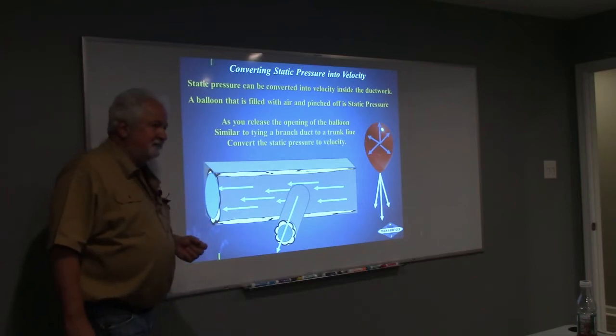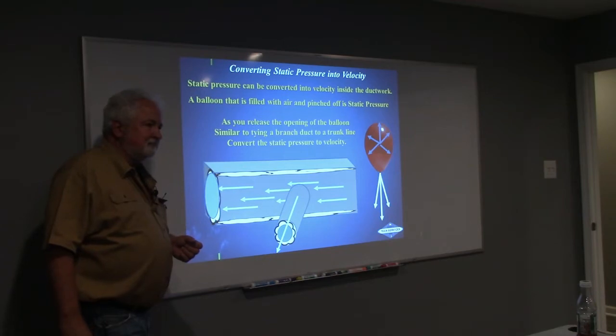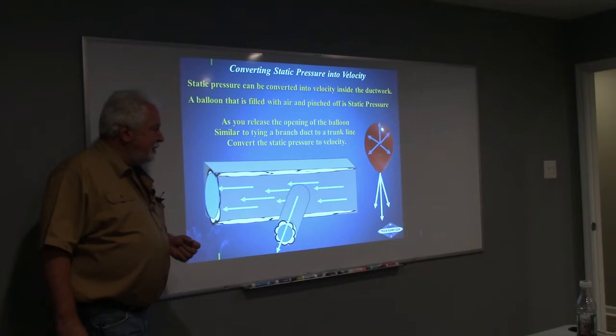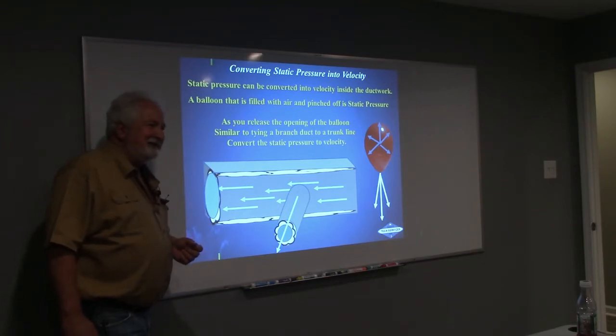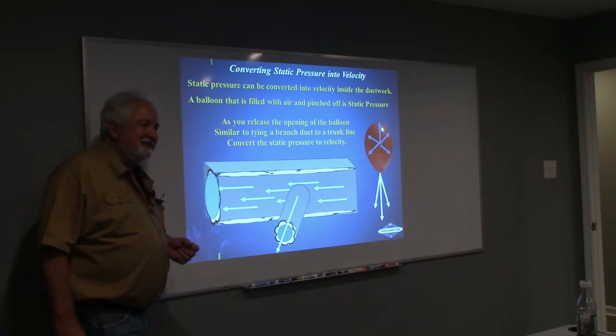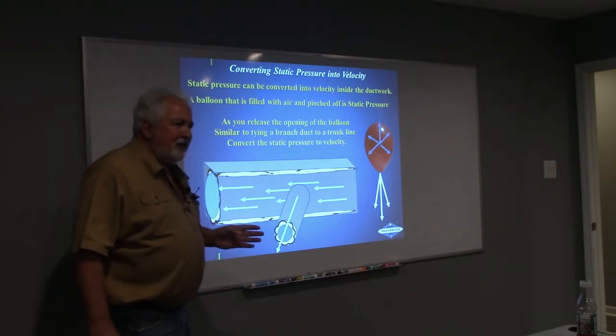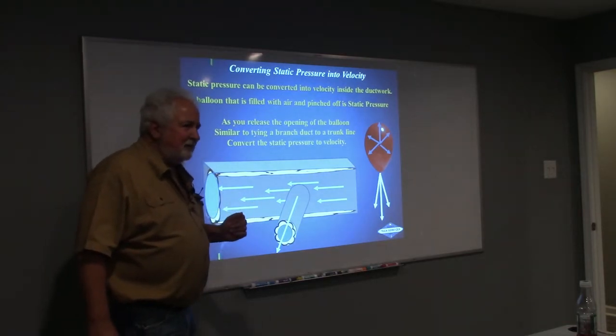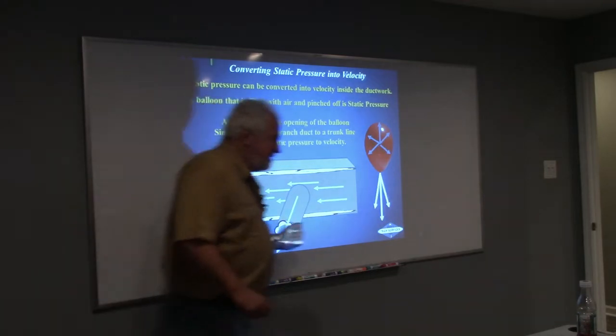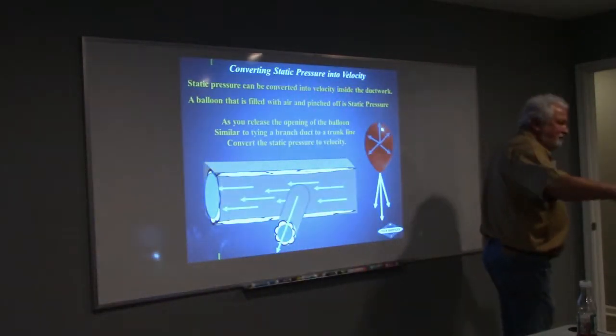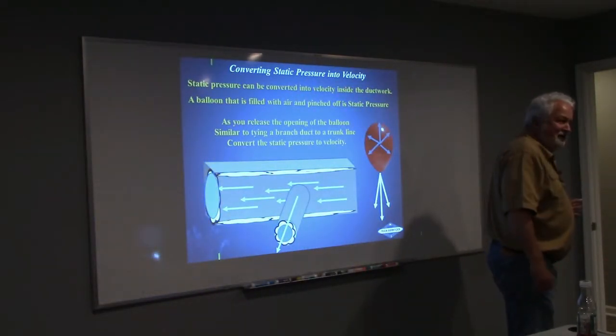So are you suggesting straight out, the first 12 inches and the last 12 inches of that plenum are off limits? Yes. I think I will suggest that, but yes, if you want to suggest it now, I'm good with that. That's normally what you do on a regular plenum straight off your unit anyway. You want to leave about a foot off of there, then start. Because how fast is it coming out right out of that plenum? That's fast. About 700 to 900 feet per minute. And if you tie in that first 12 inches, how quick is it going to make that 360 or that 180?